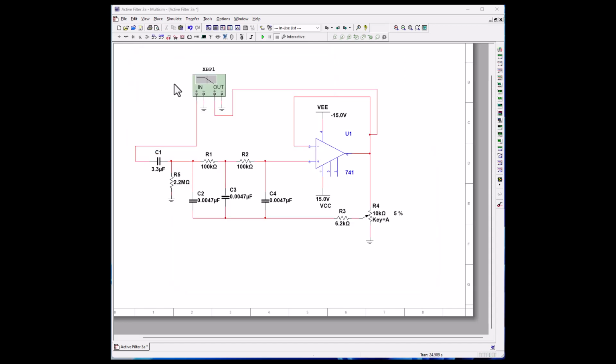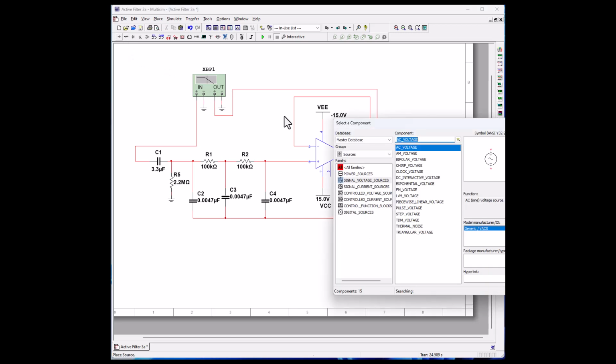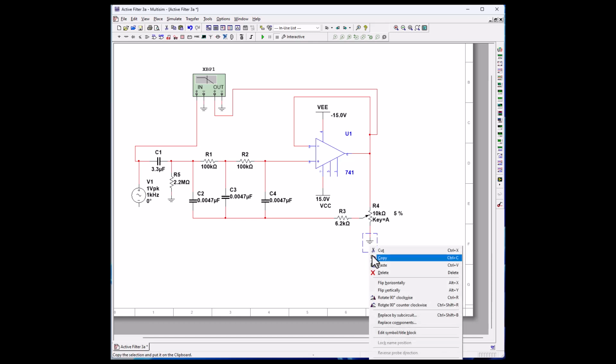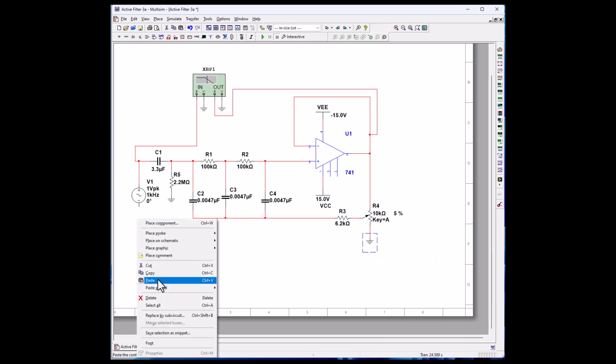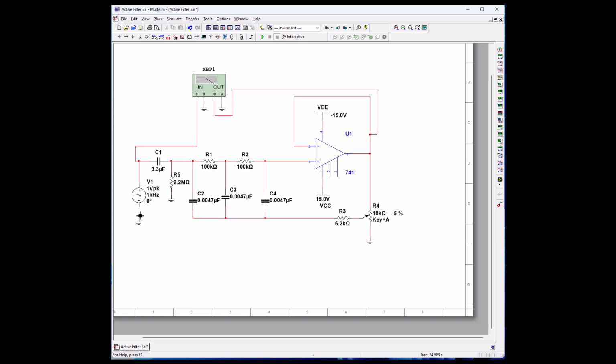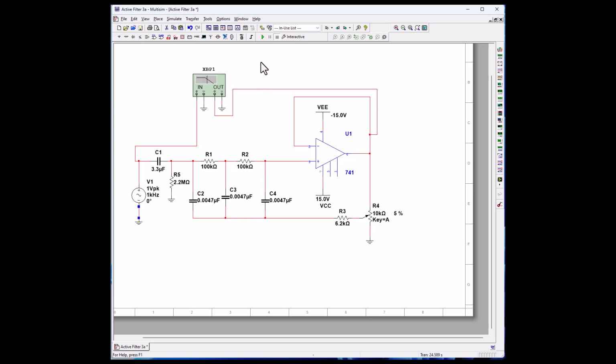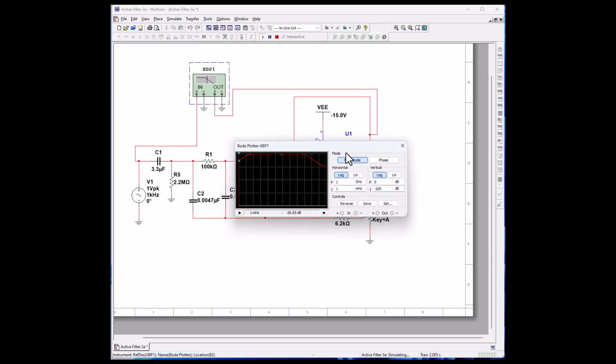Okay, back again at our Multisim, and I replaced our oscilloscope and function generator with a Bode plotter. Unfortunately, I forgot to add an AC or a sine wave here, so we're just going to go ahead and add it right now. And before I change the pot, let's go back in and double check our first answers that we had.